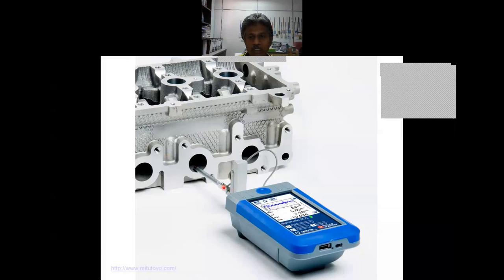So what you notice is that this instrument has a probe. At the end here, you have a small stylus that is tracked along the surface. The stylus will move along the surface through a pre-specified distance, and then the measurement is displayed here. You can see the profile here, the blue colored graph. This shows the profile of the surface, and then the measurement results are displayed here, depending on what you want to select. In this particular case, they have RSM, RZ, and so on.